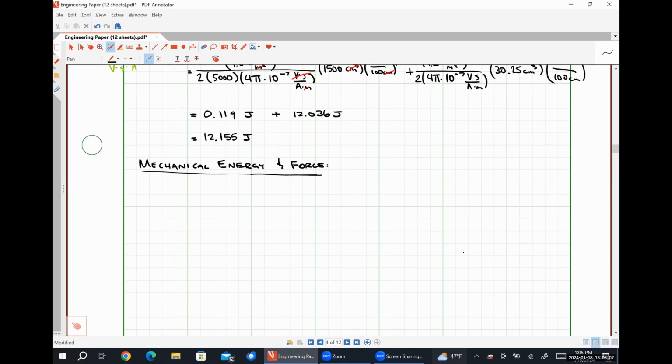So if we plot the lambda-I curves for both of these different air gap lengths, it's going to look something like this. Here's lambda on our vertical axis. Here's I on our horizontal axis. I'm going to have two curves, one like this, corresponding to x equal to x1, our original gap length, and then another curve that's going to be higher, corresponding to x equal to x2, where we have our smaller gap length.